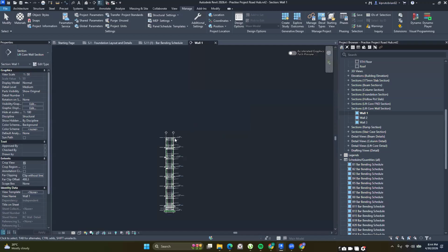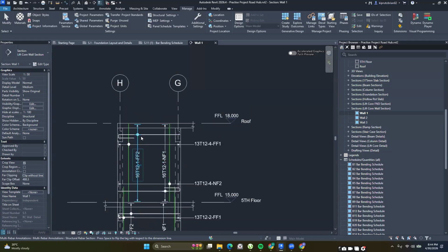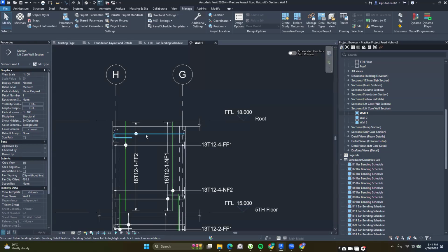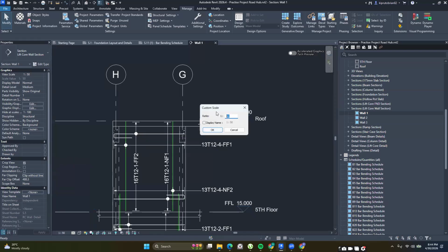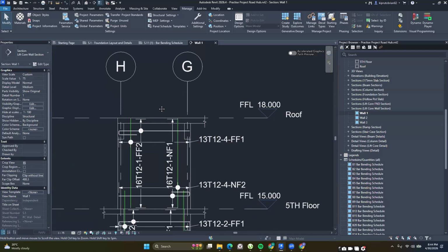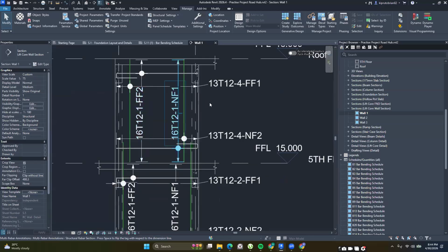So if you use this 2 millimeter dot, then with a scale of 1:50, you can have a good looking drawing, right? But if I was to reduce the scale to say 1:75 over here, then it becomes a bit chaotic. The 2 millimeter dot that looked a bit smaller in the other scale, it looks a bit larger here.